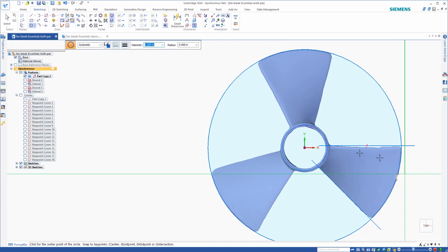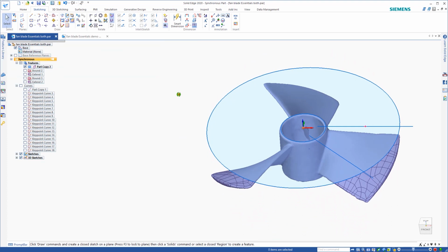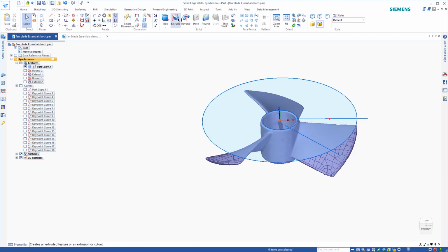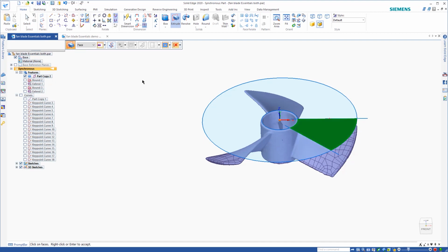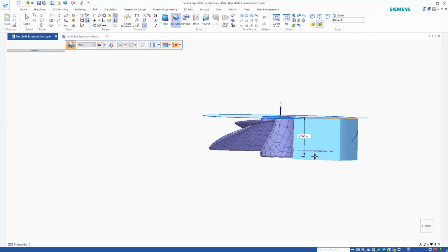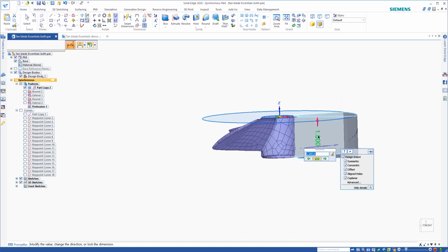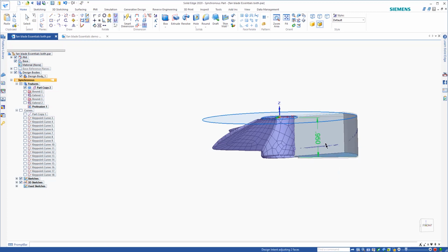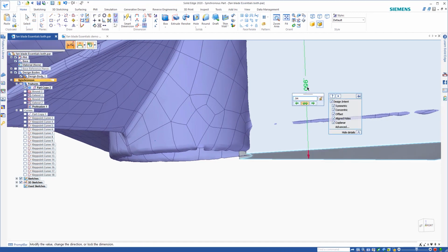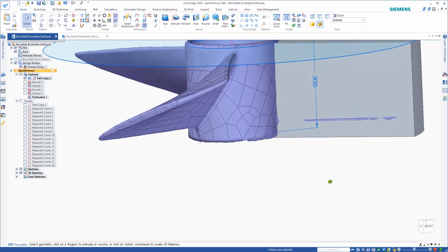So with Solid Edge, I don't have to necessarily trim all these pieces together. I can just rough out my sketch and then get out of it and then come over and do an extrusion just using that profile and select what loop that I want to use. So if I come over to click on this area right here and accept it, and then let's extrude this 1 inch. So let's actually edit that and do like 0.95 there. And you see, you can use that as a reference to see and make decisions reverse engineering how I want to.